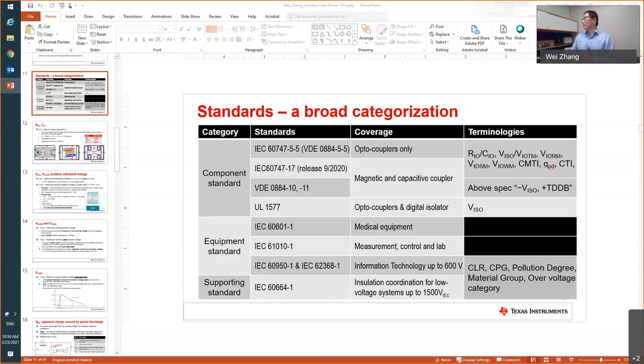If you go to IEC 60664, they clearly define that. So make sure that you cut with a certain width, and go back to the standard. Make sure it is not cutting half a millimeter, not a quarter millimeter. It's cutting 1 millimeter, or depending on the material group you are at.